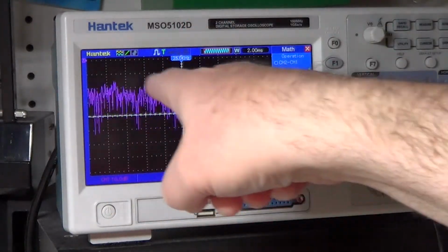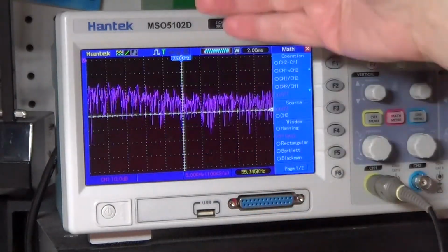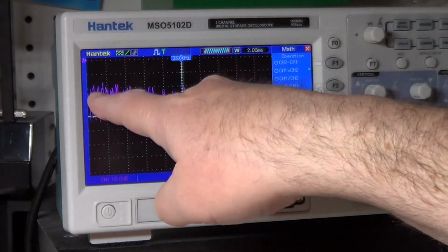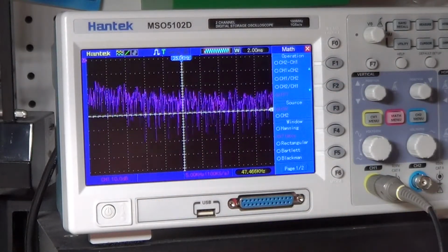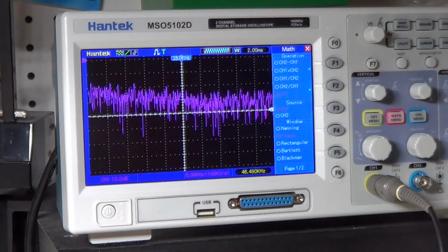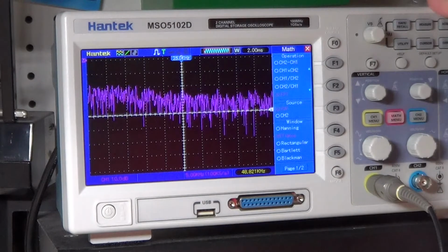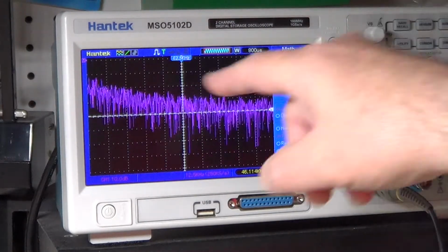You can see that now it is already in its knee of the curve, but it's still not much change from this side here, which is 0, to this side here, which is 50 kHz. And this is because there is that knee where the slope of the attenuation keeps changing. So now let's increase the range of the oscilloscope so we can see what happens at higher frequency.